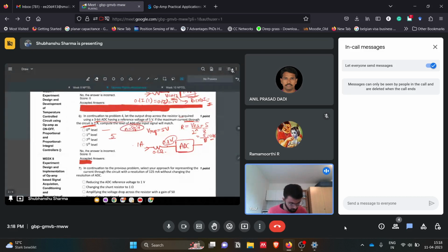If we have a 3-bit ADC, what will we have? With 3 bits, I can have a maximum of 8 levels, sir. Can I have 5 levels, fewer than 8? No, you cannot have that, because it should be a power of 2, the 2 to the power n factor. Can I have four levels, sir? Yes, 4 you can have from n equals 2 bits. If you have a 2-bit ADC, then you can have 4 levels.